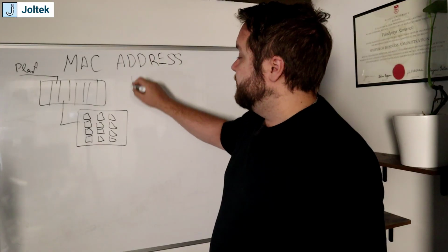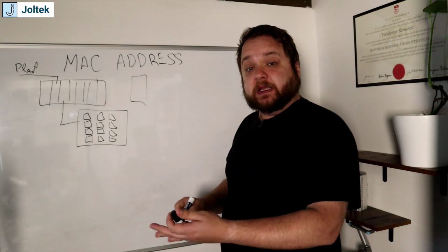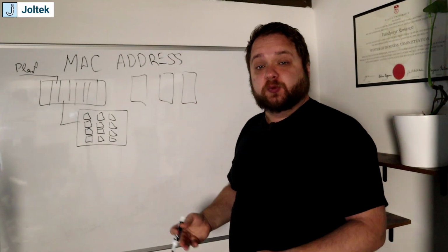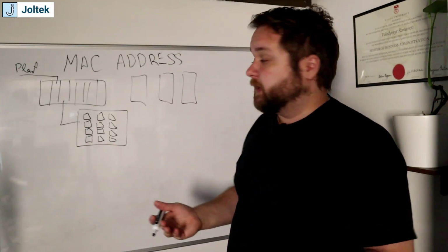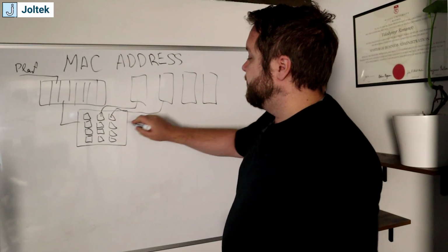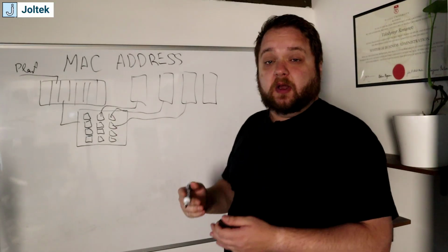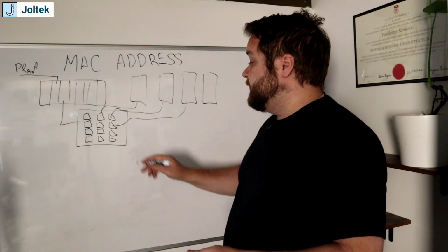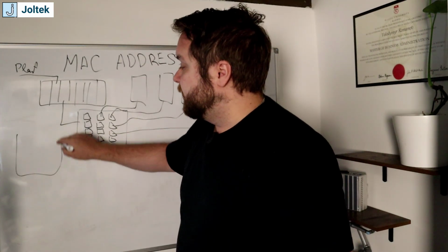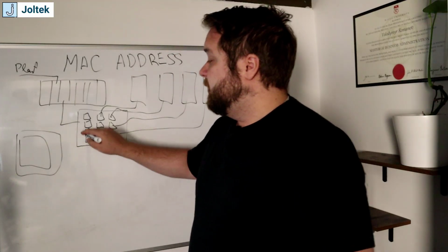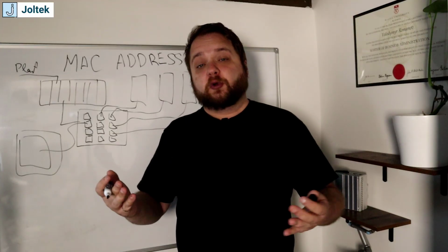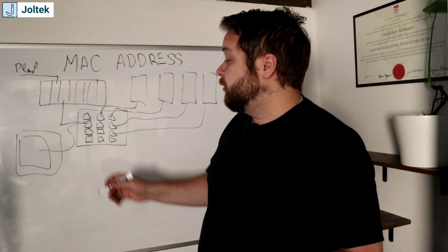Here you're going to have VFDs, just as we've seen in the lab session. Sometimes I've seen panels with hundreds of them. It could be multiple panels with a number of VFDs. All of these VFDs will usually be connected via RJ45 or a standard Ethernet cable. You will have an HMI screen on the machine, maybe even multiple HMIs. One is directly on the panel, and a few are in the field to allow for controller operation.